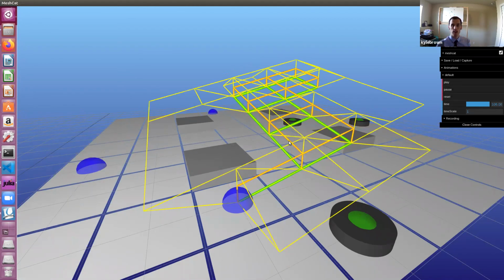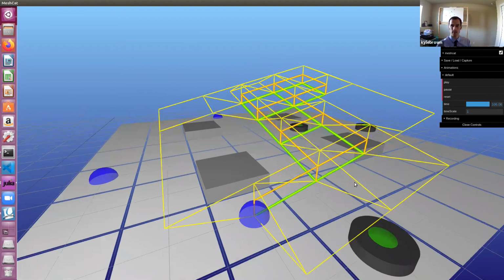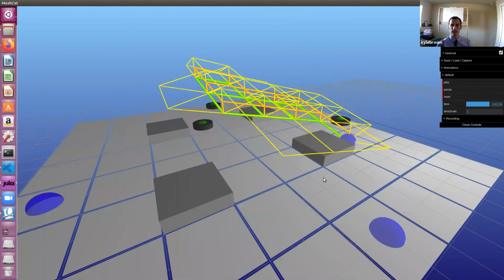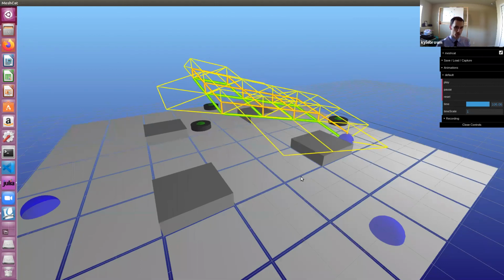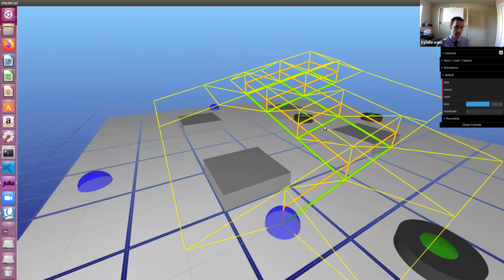And so the reason our algorithm is so effective at avoiding collisions, this low-level path planner, is because it will search through the full space of plans that do not delay, that do not run out of slack, that is, that don't cause more than the delay that's allowed, and that don't cause collisions.